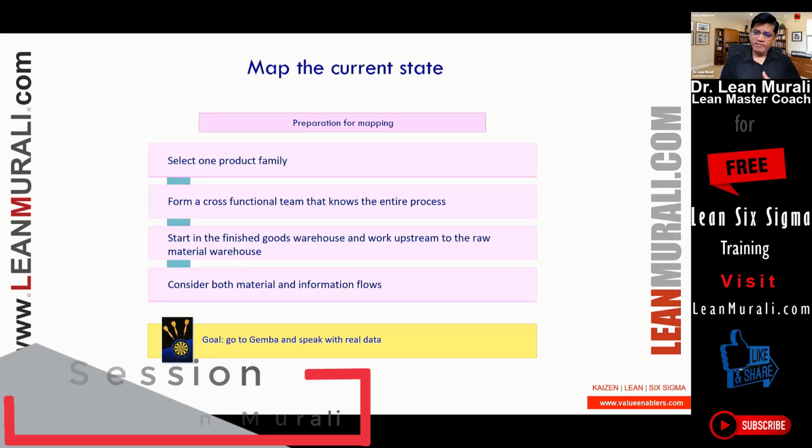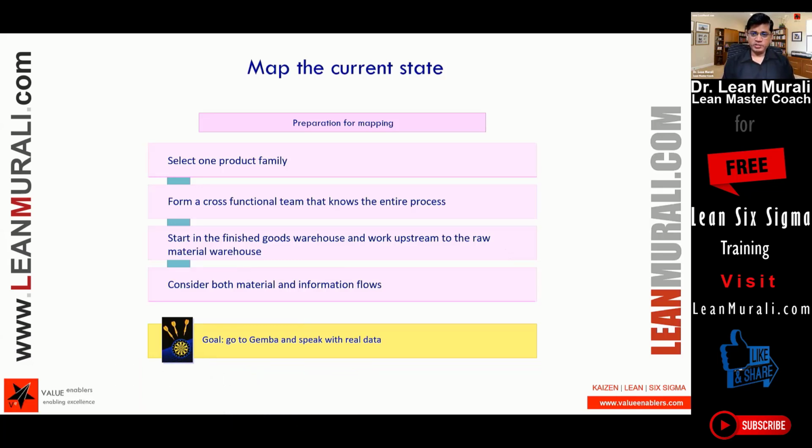Now, in each and every process, you can collect a lot of parameters. What are the process parameters that you can collect? Dimensions, cycle time, setting time, temperature, pressure, output, inventory before, after, measuring time, required quantity, delays, quality, CTQ, CTP, critical to process, critical to quality, rejection, rework data, makes sense.